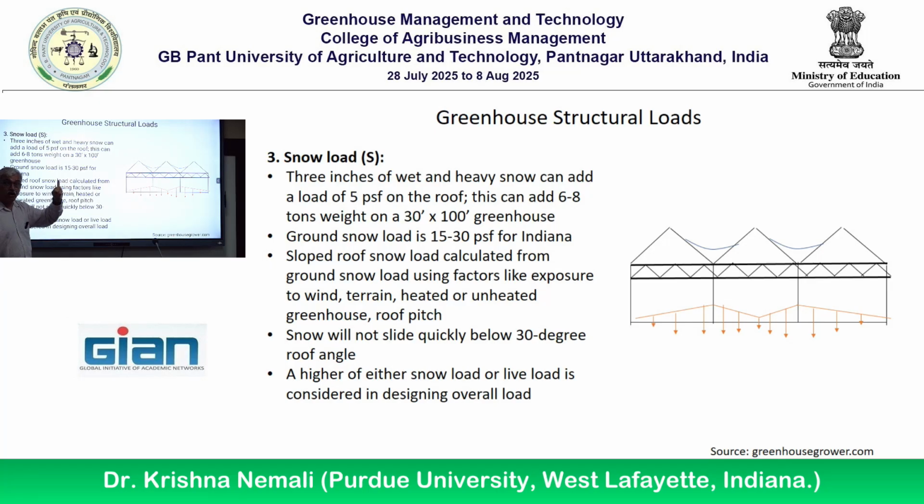Okay. So dead load, everybody understand dead load? It's a permanent structure, right? Glazing material, roofing material, everything. Then there is live load, people working, plants hung to this. These are kind of like at one point. And then now we have snow load. These three things already. And the fourth one, can anybody expect what the fourth one is? Well, kind of rain and snow. Rain will go away, so it probably won't add a lot of weight on it. It falls. Something that stays for some time is what the load is about, right? Rain falls, but it flows away. But what's the fourth thing that's constantly hitting the greenhouses?